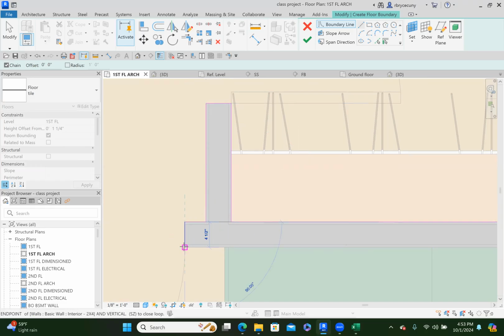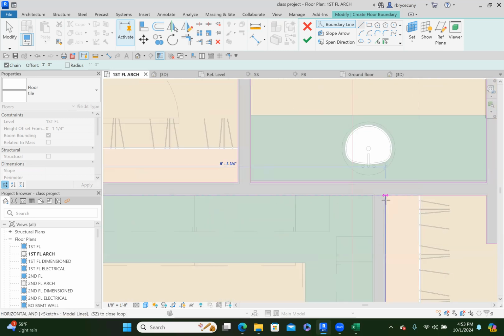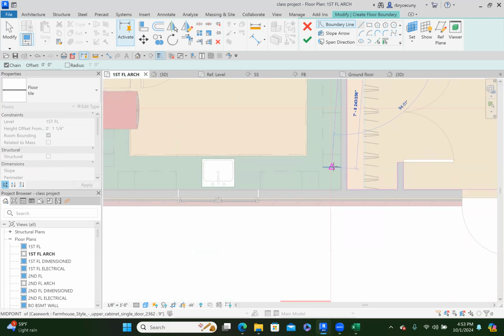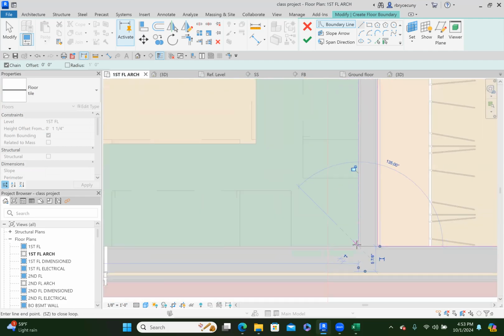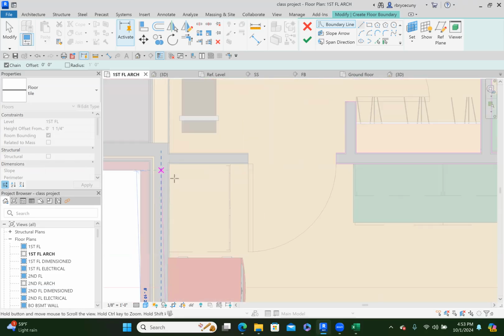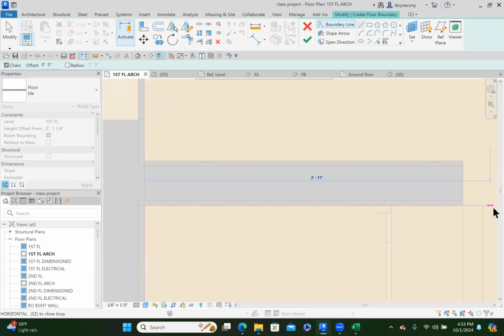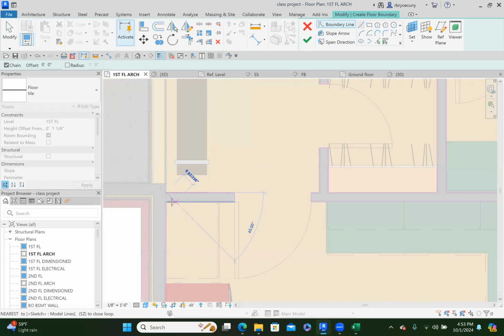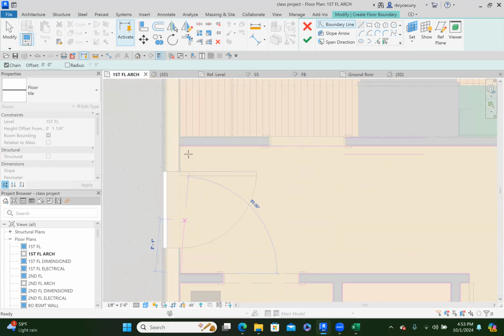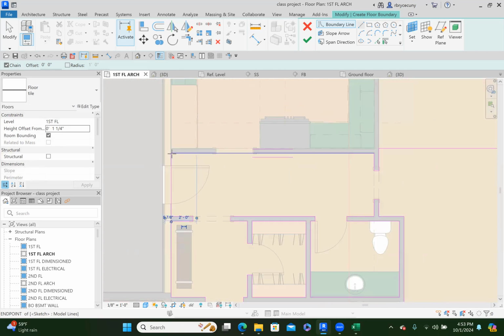Now remember, I take the tile or the finished floor right up to the wall, because someone might change the cabinetry later on in this house if it were really being constructed. And if they took out the existing cabinetry and didn't find tile all the way up to the wall, they might have a difficult time patching in new tile. It's that much additional expense.